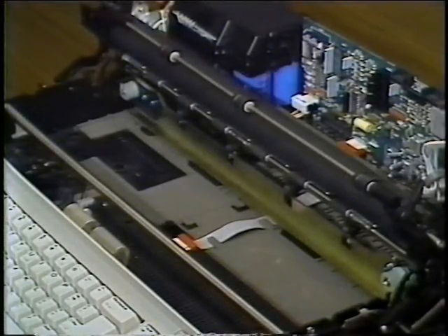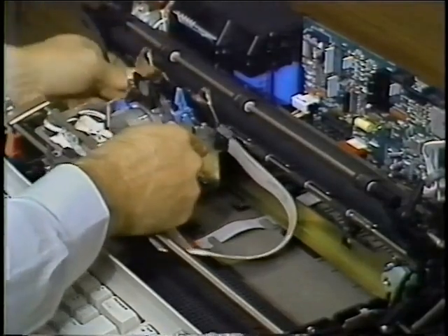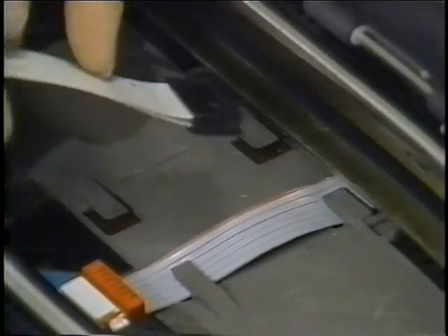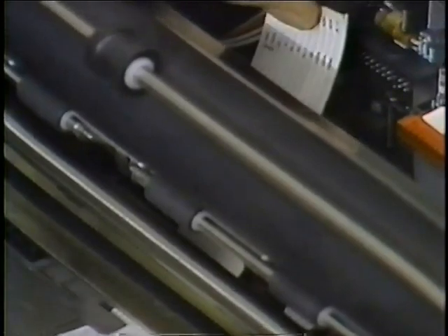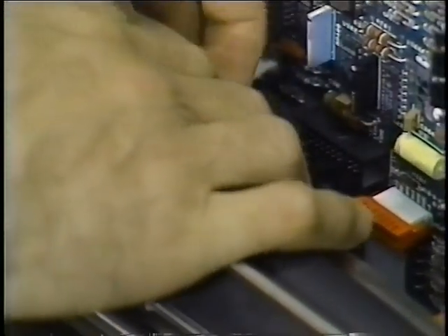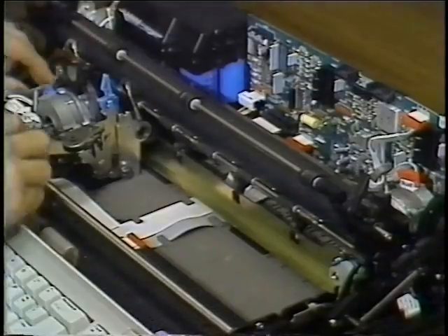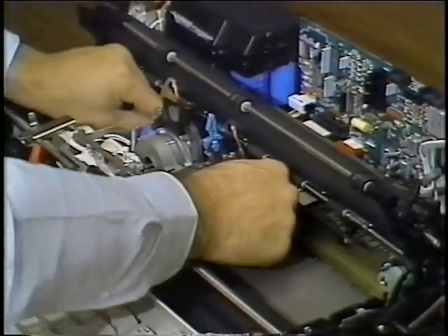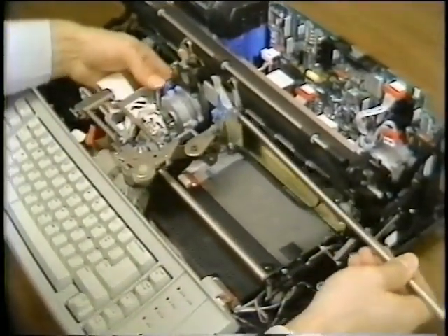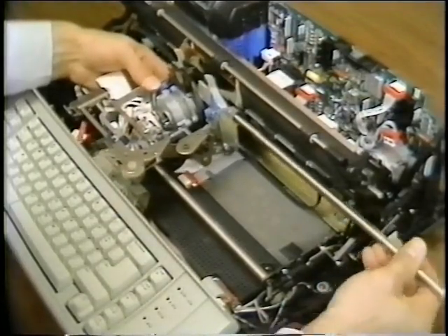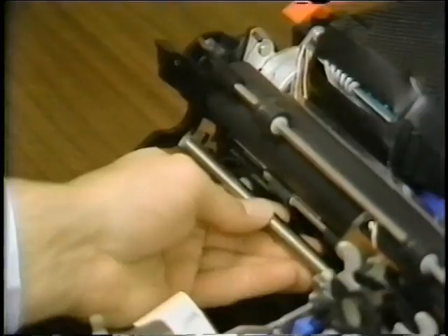To reinstall the carrier, set the carrier in the machine and slide the carrier cable under the machine frame. Work the cable under the clips in the base of the machine, then plug the carrier cable connector J4P into the printer board. Hold the carrier shaft so the end with the large flat is to the right. Then slide the shaft through the carrier from the right side. Next, push the carrier shaft into the right side frame and slide it through until it stops. Do not force the shaft beyond the stop.